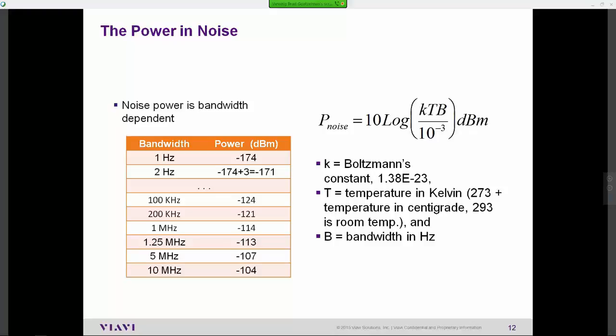So what this table further shows is that as you move through different bandwidths that are oftentimes relative to the different technologies, these in fact become the theoretical starting point for how much power you can otherwise measure. If you ever use a piece of test equipment and they measure below this, you immediately know there's something wrong, because in fact, these are theoretical.